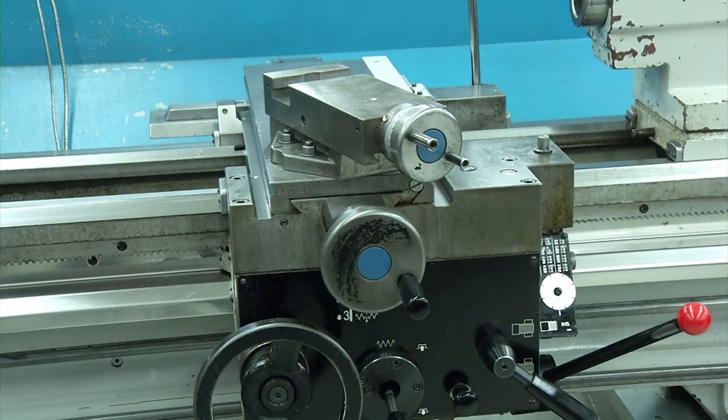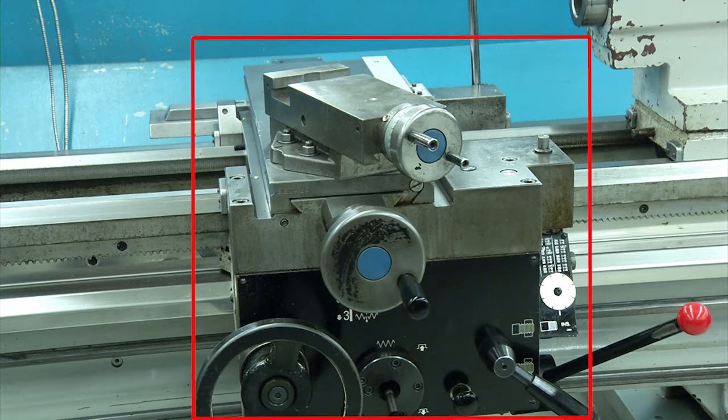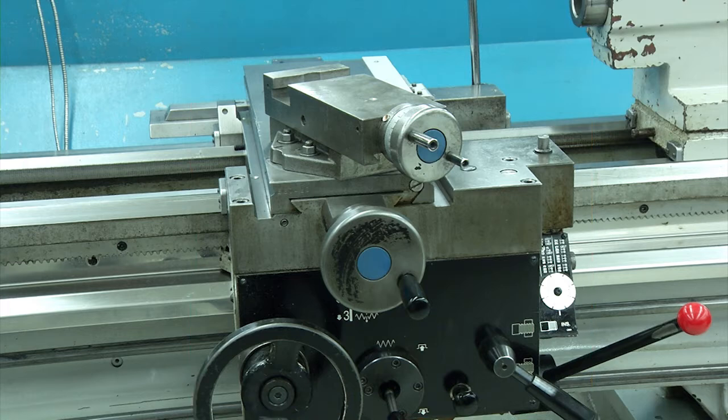The carriage houses the saddle, the cross slide, and the apron. The main function of the carriage is to position the tool along the lathe bed. The saddle sits on top of the apron. It rides along the bedways and guides the apron in cross slide. The apron houses the components to control and drive the cross slide and the saddle. The apron rides along the bedways.